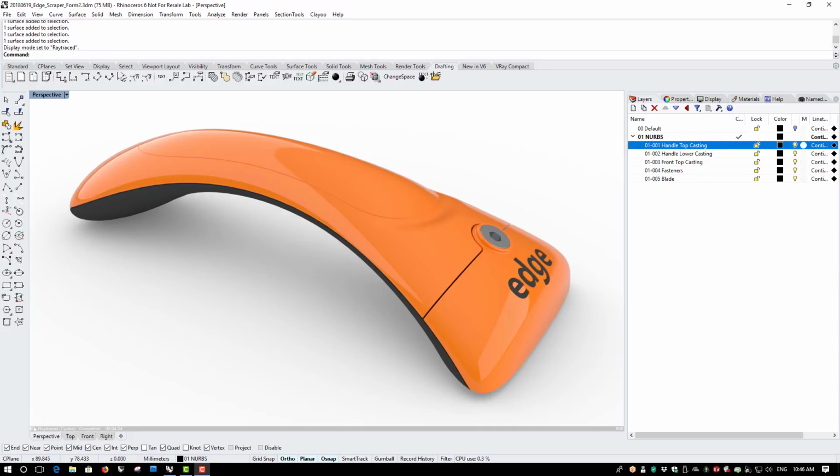The overriding principle is that the geometry needs to be built correctly in Rhino before creating the mesh STL file. Whilst it is possible to fix issues on a mesh file in Rhino, it is much easier to do this on the original NURBS geometry.